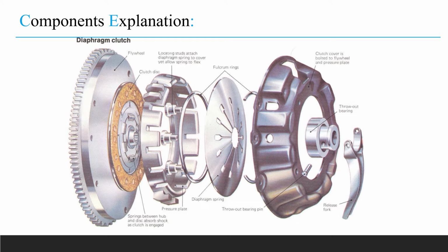The flywheel is equipped with a friction surface, and so is the disc clutch on both sides. The friction surfaces are made of ceramics or substances that cause a high coefficient of friction. When and only when both friction surfaces are connected, the clutch disc rotates. The disc clutch itself is also made of important subcomponents such as the hub, cover plate, and the rivet.